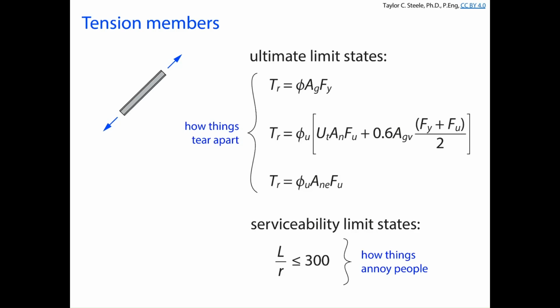And then the other day we talked about this bigger, longer equation, which was another way that you can fracture a connection, except in this case, we don't have pure tension, but we have some tension and we have some shear. Okay. So in terms of covering these three equations and what they mean for the failure of tension members at the ultimate limit states, we've covered all of that material today.